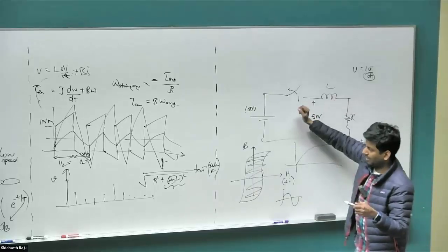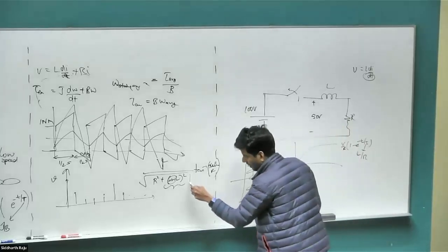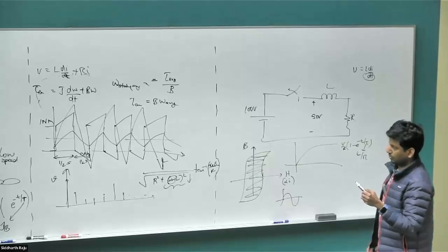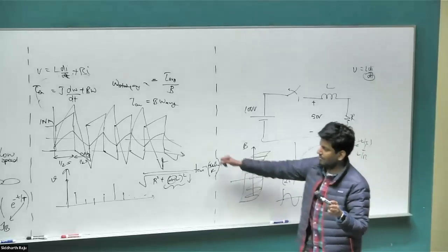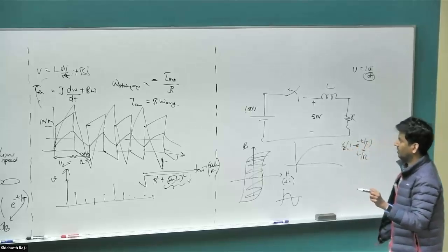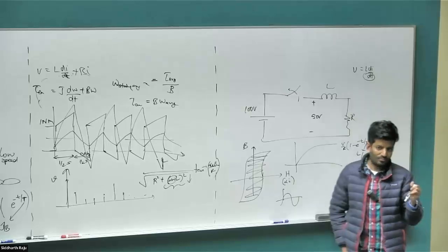So you want to go to as high a switching frequency as possible, so that you can reduce the harmonic content in your current, so that you can reduce your losses and make it more efficient, and so forth. And there are other issues as well, like EMI, EMC that come out because of these large varying waveforms. We don't need to worry about it too much. Okay, so you want to go to higher switching frequency. What is the solution then?